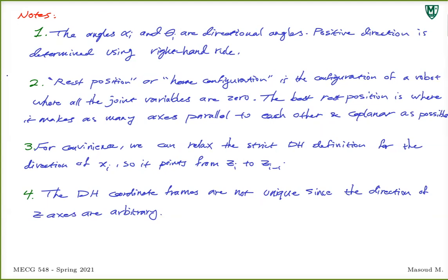All right, so these four, there are two more that we have to mention because we're going to use them when we are setting the frames. One important thing is about the base frame, right? You will see that following rules, you can set up coordinates for frames, because for any frame to set up where it is and its orientation, we need the frame before that, right?